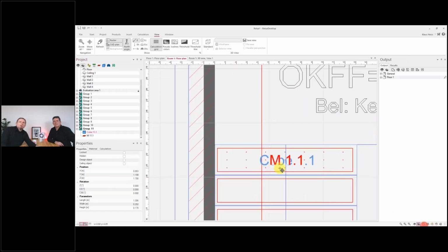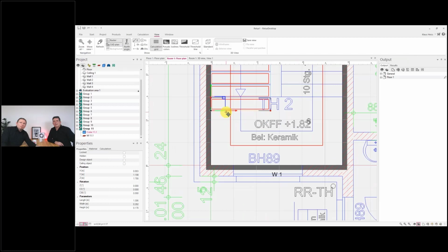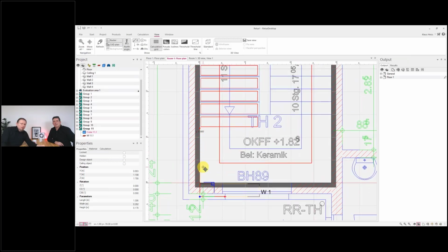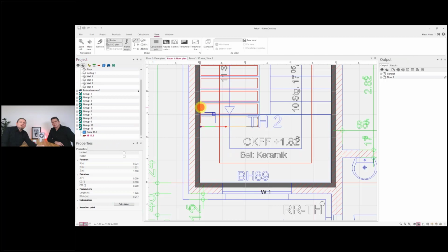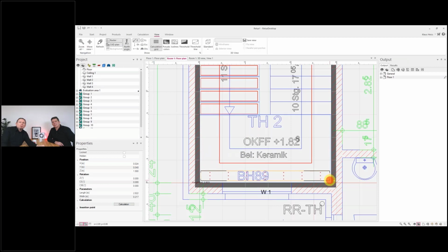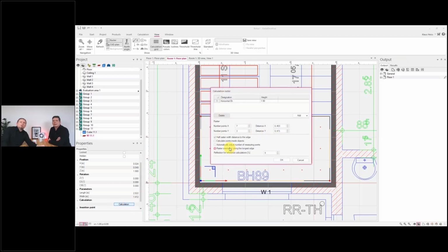This is better in 2D. Here I move this to this area. Try to do it precisely. And here I do the extension in this direction, and here in that direction. And don't forget the measuring surface, that you also need to adapt this to the size of the podest. And here we should also think about the grid. I'm going to change the grid to automatic.